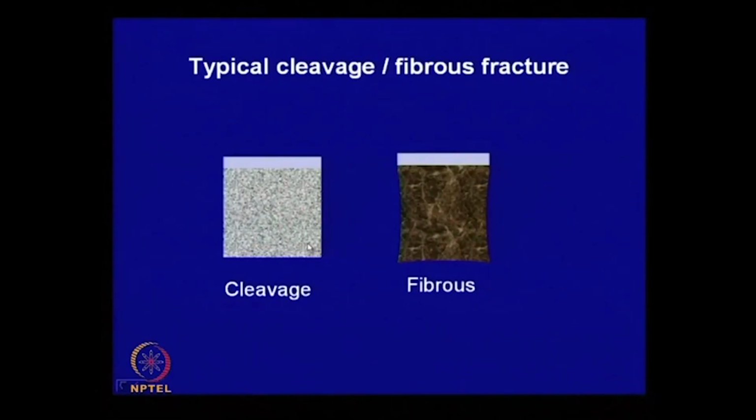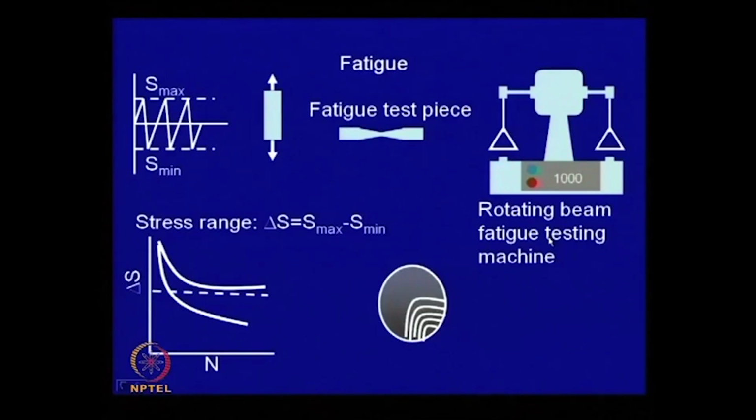And the typical surface of the fracture is shown here, this is the typical appearance of the fracture, and particularly look at this. There is a large deformation around that notch root, which is a sign of plastic deformation and ductile fracture.